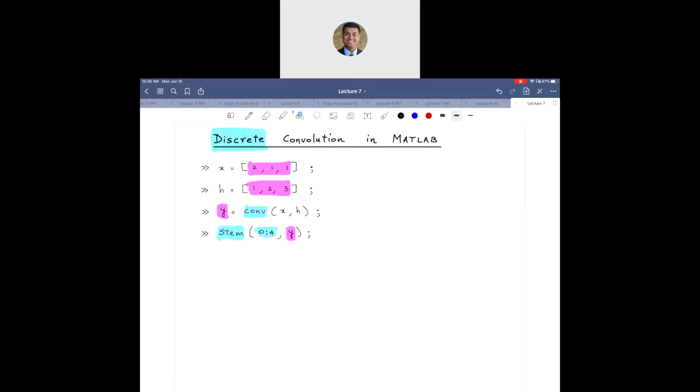So let me do a separation here and say sampling time, say Ts equals, say, 1e minus 3, which is 1 millisecond. And that's my sampling time, the time interval between any two values. And I can form a time vector here, which goes from 0 to, for example, 5 in steps of 1 millisecond, Ts.